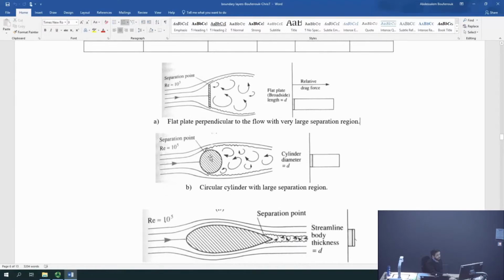Kind of a similar situation, not as bad, but almost the same. If you have a cylinder like this, and you have flow coming, particularly at high Reynolds numbers, then again the flow separates rather quickly and you get a thick wake and a lot of eddies as well. In this case, your pressure drag is large. So I think you are starting to see the picture. Whenever you see a lot of flow separation around any surface, like an airfoil or wing, you know your pressure drag is very high.